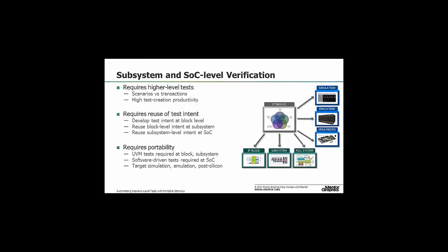Unfortunately, it's not been as successful at the SOC level, and the reason is that when you move up to SOC level, you involve one or more processors running software, and UVM, as it is today, has very little provision for expanding the tests to also involve software. So many times companies regularly use software-driven tests at SOC level, test programs running on the processor, but when they develop those tests, they start with a blank page. They can't really reuse what's done at the block level, which is, of course, a big disadvantage.